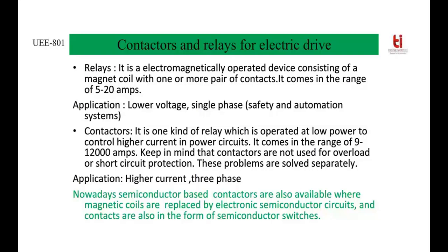So nowadays these relays and contactors are being replaced by power electronic switches. The reason is that the switches are very fast, and available in a wide range from low power to high power applications. High power thyristor, low power transistor or MOSFET, and for medium power you can use IGBT. Another advantage is that the switches are highly reliable, highly efficient, very low in cost, and can be controlled easily by providing suitable pulses across the bases or gates of the circuits.